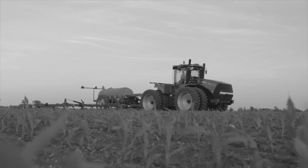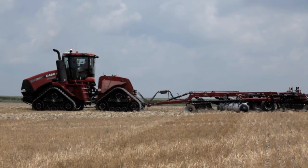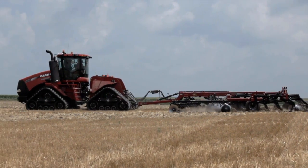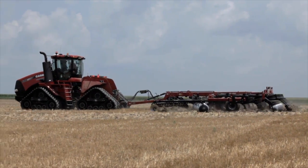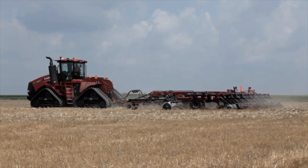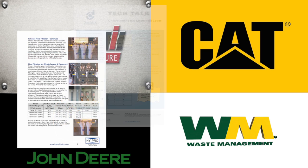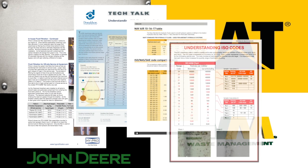Extended equipment downtime caused by labor-intensive and outdated procedures, and an increase in repeat system failures caused by contamination. Advancing technology has made contamination a much more sophisticated problem to control. The fluid power industry is changing to accommodate these issues. Manufacturers are now publishing oil cleanliness standards for their machinery and components. They are mandating conformance and rejecting warranty claims for contamination-related failures.